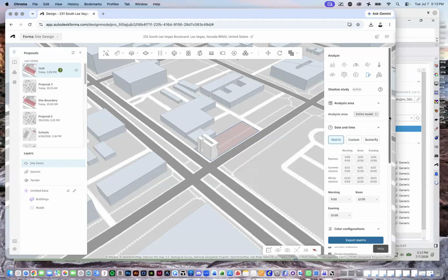I mean, there are plenty of workflows to just bring a native Rhino file into Revit, but if everything lines up and is in Forma, then we can just bring an IFC file out, and then just import that bad boy into Revit. It'll be the right scale, it'll be the right units. It's IFC, it's international, it's universal. That's the universal BIM standard, building information model standard. So if you need to share a file and someone's not using Revit, you can't give them an RVT file, you can give them an IFC.